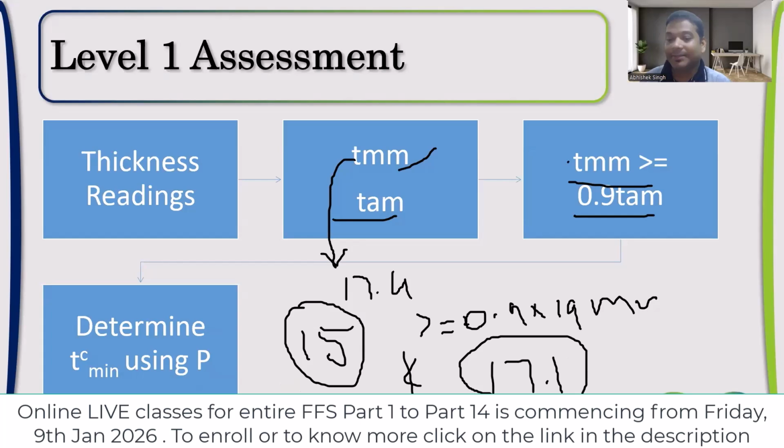Gaurav, and to others also, does it make sense? If some point is completely lesser than the average, it indicates that the procedure I'm using for general metal loss assumes that the loss of my material is very uniform. If it is a uniform thickness, will some points be very low in thickness? The answer is no. More or less, all of them will be at similar levels. The variation in points will not be very high. If it is very high, it is indicating a local metal loss. Okay. Hope it makes sense. Gaurav, this was your question, so I hope it makes sense.